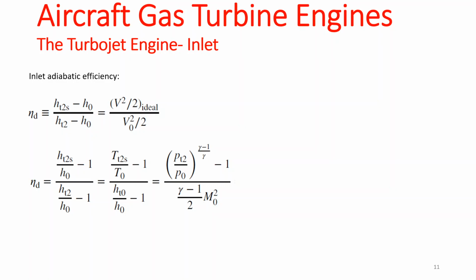So we do these replacements, and we can rearrange the equation, and that will give you the pressure ratio. That's going to be your inlet, your diffuser exit. I'm going to call the inlet diffuser, not to confuse the inlet and outlets, right?